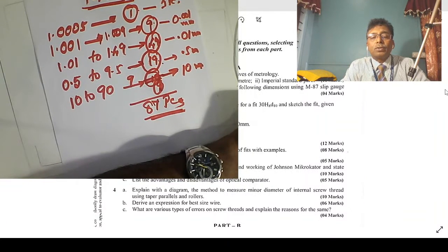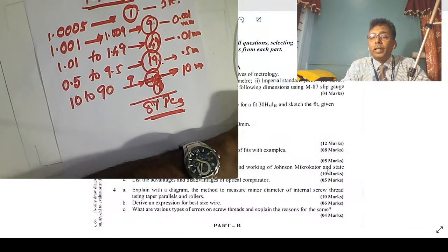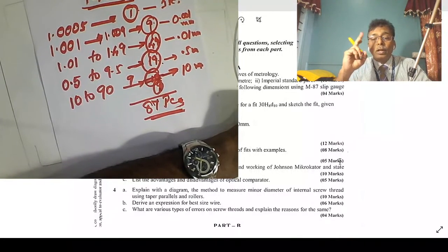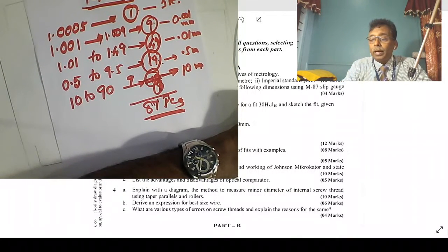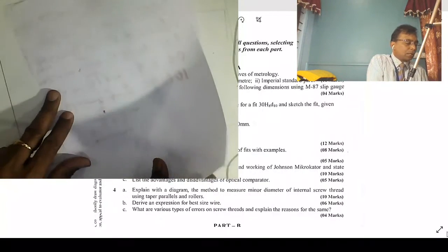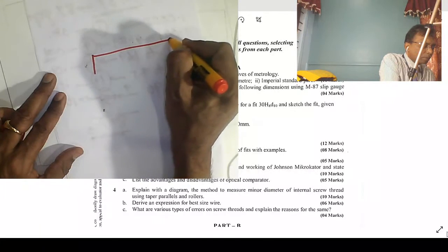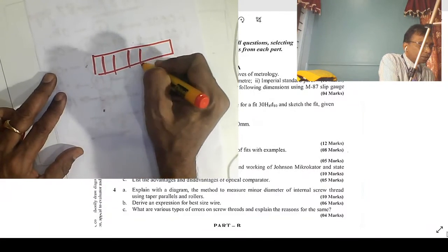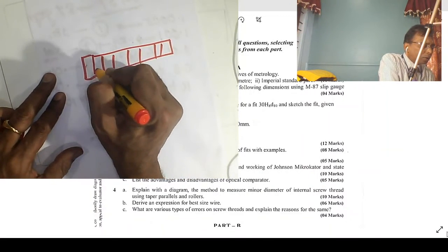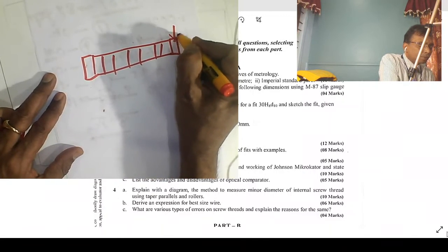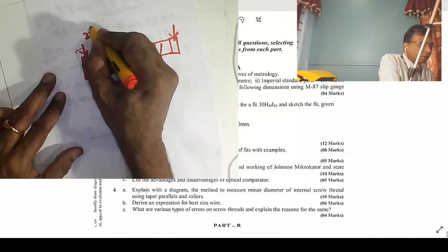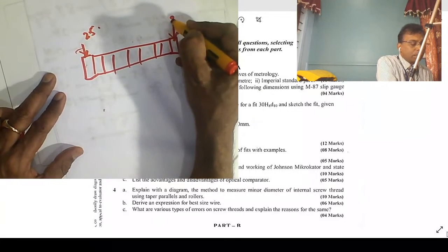Let us see, I think I have solved one problem. 92.357. The given question says 92.357 using 2 protection slip gauges of 2.5 mm each. These protection slip gauges are end gauges. Supposing you build these various combinations, you add 2.5 mm end gauges. This is given as 2.5 mm and another is 2.5 mm.